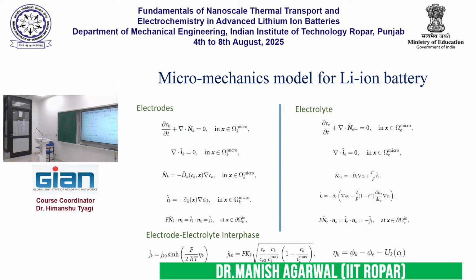Is there any equivalent of the transference number in heat transfer? No, I don't think so. In heat transfer, the right hand side will only have the first term. The second term will not be there, because the amount of heat flux does not depend on the absolute temperature, it only depends on the gradient. So this will not be there.